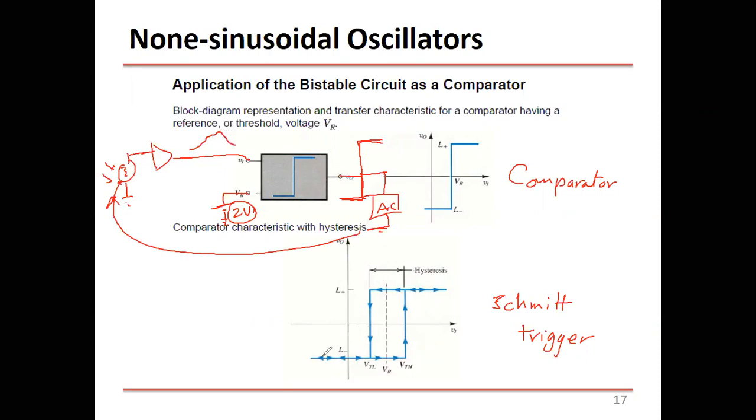This is the same thing, but the direction of going forward is different than the direction of going backward. What do you think? Which one do you think is better, this one or this one? VR here corresponds to the room temperature that you would like to set, the set point. So VR corresponds to a temperature of, let's say, I'm used to Celsius, so I don't know how much Fahrenheit, 70 degrees Fahrenheit. So you set your thermostat at 70 degrees Fahrenheit.